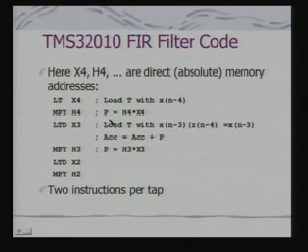When I multiply, I have a P register below the multiplier block, so that data goes into the P register. Then I have an instruction called LTD X3, which loads T with the next sample and also loads my accumulator with accumulator plus P. This can be done because these are at two different parts of the data path.